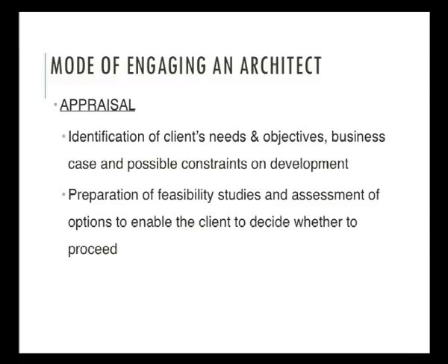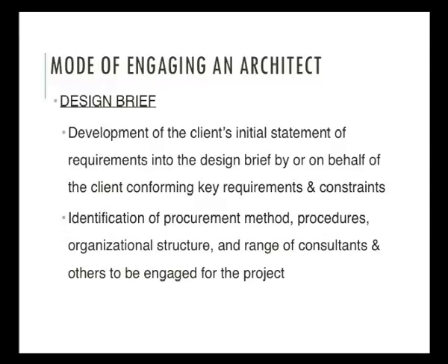Preparation of the feasibility studies and assessments of the options to enable the client to decide whether to proceed or not. Then the second important stage is designing a brief: development of the client's initial statement of requirements into a design brief by or on behalf of the client, confirming key requirements and constraints. Identification of the procurement method is important, as are procedures, organizational structures and the range of consultants and others to be engaged on the project. These are important strategies for designing a brief. So the client's needs will be listed out like that and the brief will be made ready.